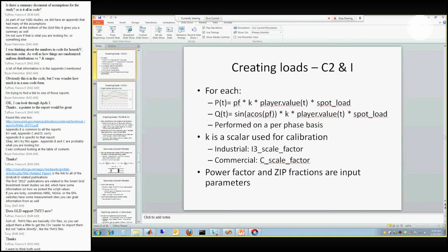Yeah, basically, what you want to do is somehow increase the impedance across, especially the trunk lines themselves. If you can get those main primary lines with increased impedance, then that'll very quickly show you some large voltage drops. Okay. We'll try putting some speaker wire in there and see what happens. Okay, thanks. Yeah, no problem.